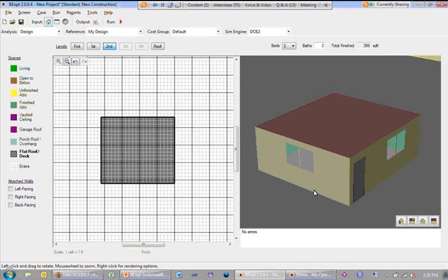If it's, what did you say, a 2-degree pitch? Well, just pulling out a number, I think of all of the retrofit Baltimore, Philadelphia, metropolitan row houses that all pitch to one end direction, and they're all row buildings. I also think of out here in the Southwest, all of our Adobe-style, Santa Fe-style houses with single pitch roof off the back with a parapet wall around it. And where in the front of the building it might have a quote-unquote roof cavity of 3 feet, and in the back it might have 6 inches, depending on the slope and the depth of the building.